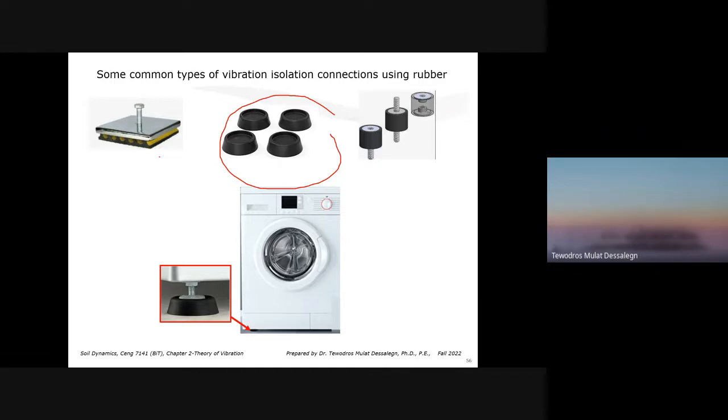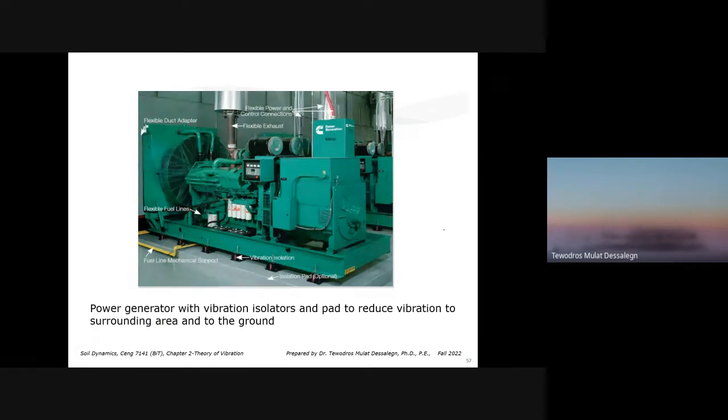So you can have various kinds of dampers at different places. All they do is they damp out the motion. They reduce the force to be transmitted. Let's say this equipment, this is like a motor or a generator or anything. When it vibrates, there are forces passing to the floor. So you can see these vibration isolations. You have rubber-made materials or a pad, isolation pad. All this pad and vibration materials, all they do is they isolate whatever vibration you have from this equipment, they damp it out. So it doesn't transfer to the floor or the concrete or the foundation.